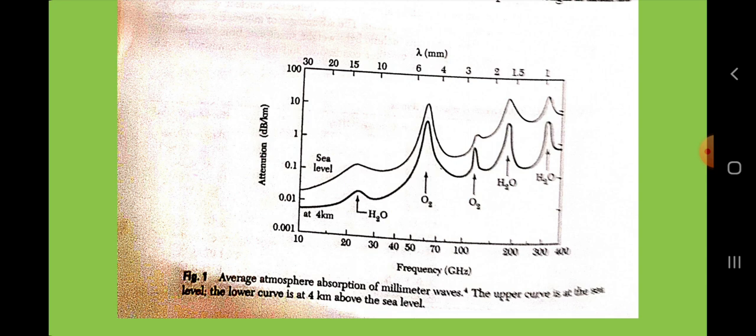The resonant cavity is a metal walled chamber made of low resistivity materials enclosing a good dielectric, for example vacuum, dry air, and dry nitrogen. It is analogous to a section of waveguide with both ends shorted and has a means of injecting energy into or extracting energy from the cavity. The cavity supports both TE, transverse electric, and transverse magnetic modes of propagation. The electromagnetic wave is confined by the wall of the cavity. Energy stored in the electric field represents the capacitance, whereas the energy stored in the magnetic field represents the inductance. Both elements of the LC tuned resonant tank circuit are present in the cavity.